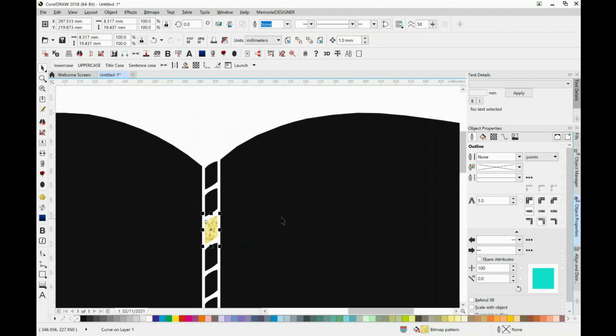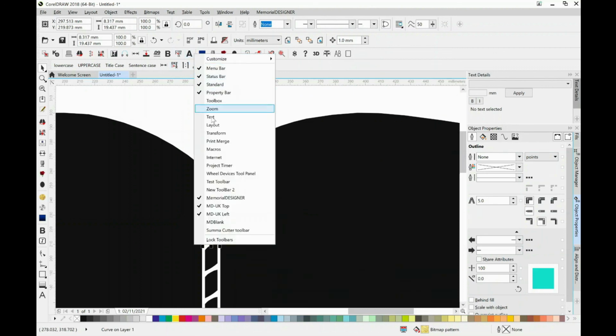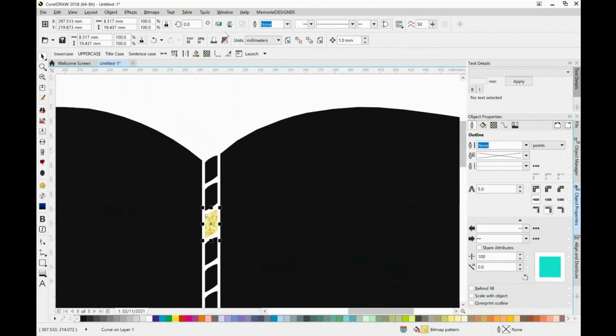I hope that helps. If you want to use dxffix, I can recommend dragging and dropping it onto your own toolbar here so that you don't get too many features on there. I try to keep this down to a minimum if I can, and I certainly don't want to throw dxffix onto everybody's desktops. So if you press the Alt button, you can just drag dxffix and stick it alongside the auto size button if you so desire, and then hide that toolbar because there's an awful lot going on there.